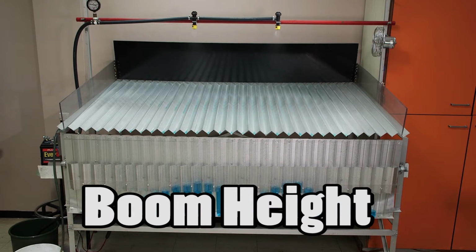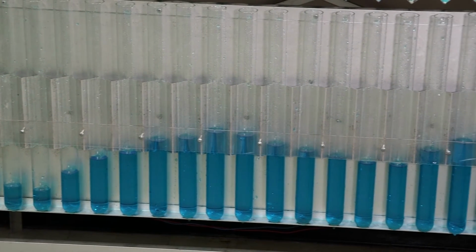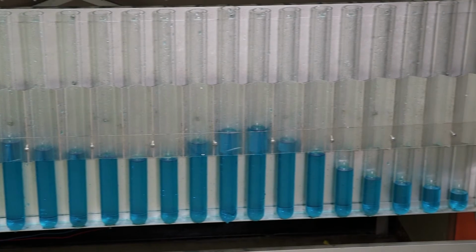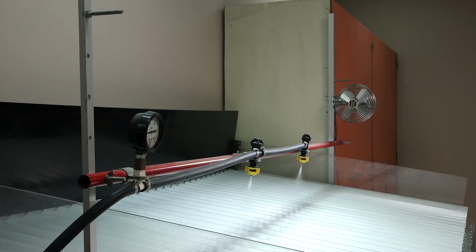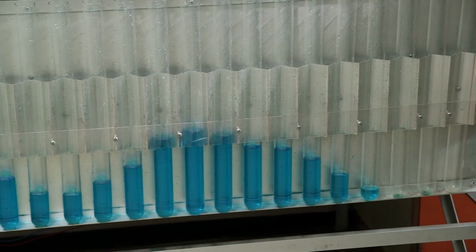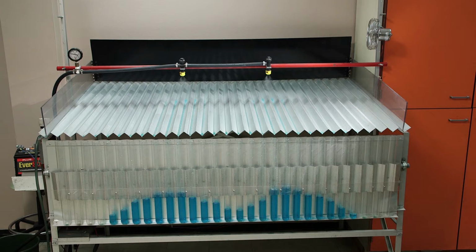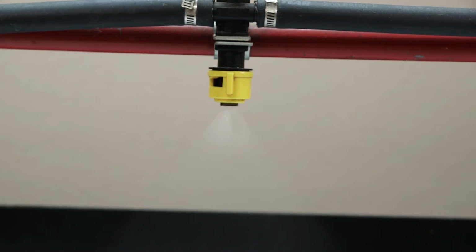Boom height is another factor that can affect uniformity of spray application. Spraying at the current boom height results in a fairly uniform overlap, exhibited by the water distribution, particularly at the center of the table. Now the boom height will be lowered while spacing between the nozzles remains the same. The lower boom height results in a spray pattern with 2 separate peaks and an uneven application. The benefit of a lower boom height is reduced drift. Selecting nozzles with a different fan angle and adjusting pressure can improve application uniformity when using lower boom heights.